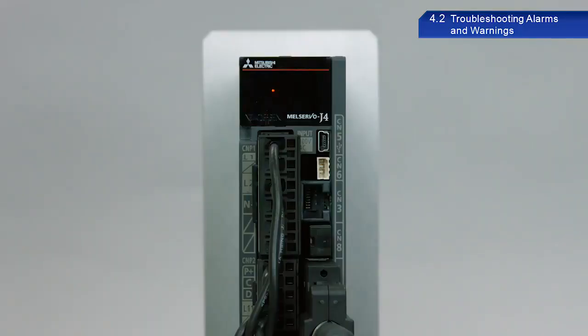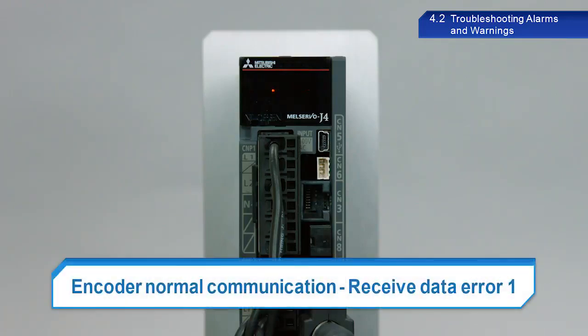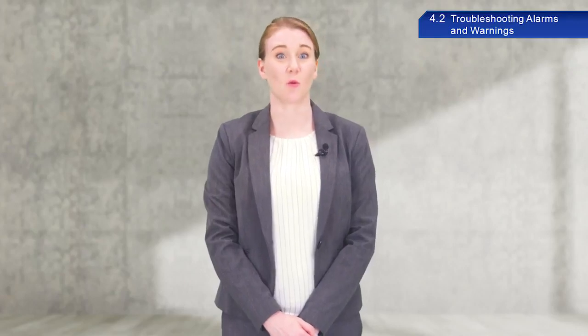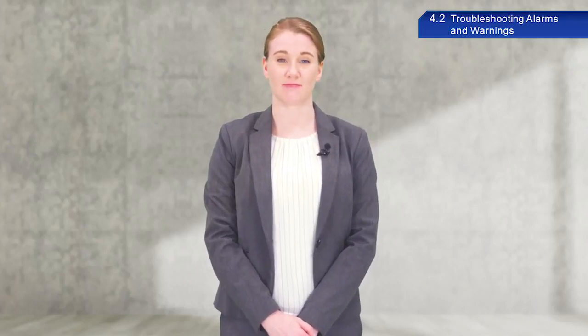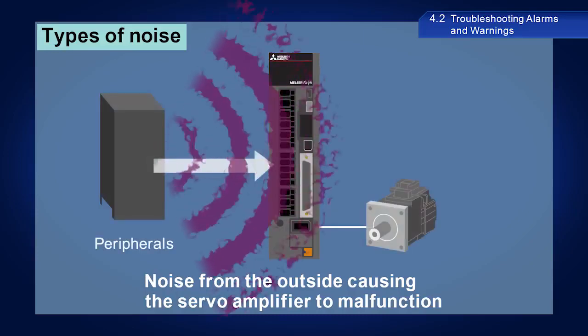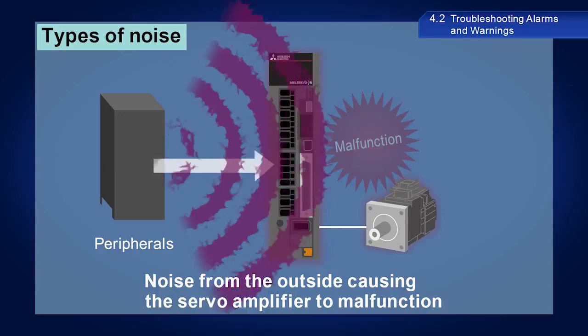The alarm with an alarm code of 20.1 is the Encoder Normal Communication Receive Data Error 1 alarm. This alarm is caused by environmental factors such as noise. Noise can affect various electronic devices and can be generated from a wide range of sources. The intrusion of external noise can cause incorrect servo amplifier operation.